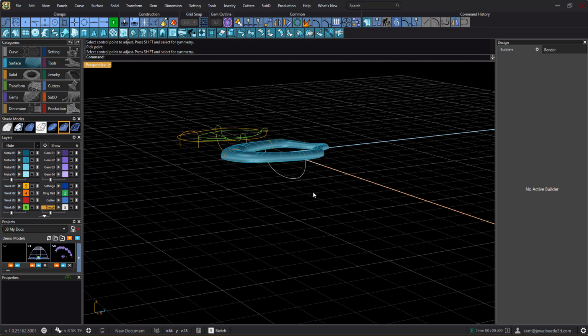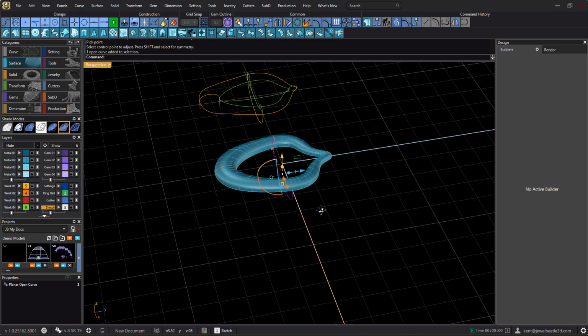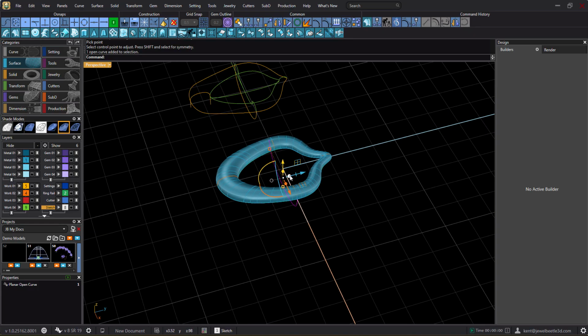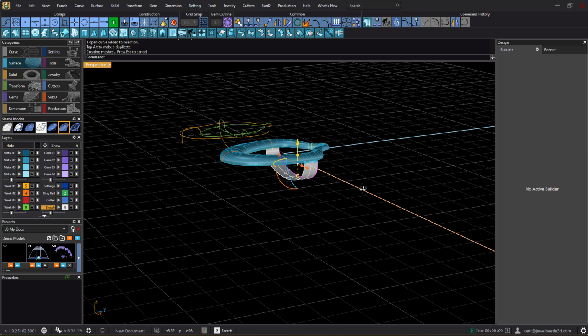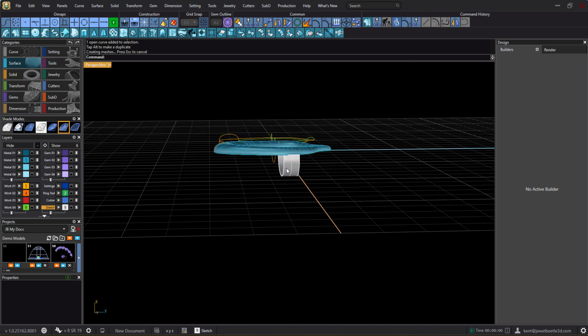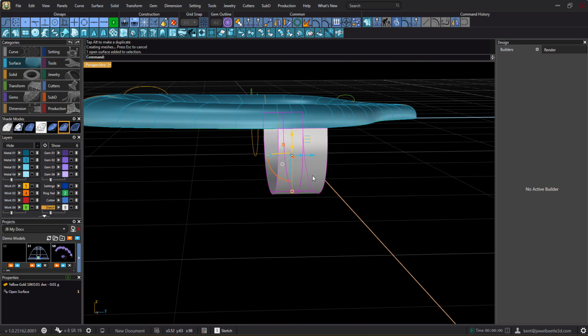And what I did is in Rhino 8, okay, here's extrude, and open extrude. Well, this one's going to be open anyway because it's just a curve, but an open extrude, as you can see, is holding down control and moving that. And all I have to do is move just a little bit to make a surface. Okay.